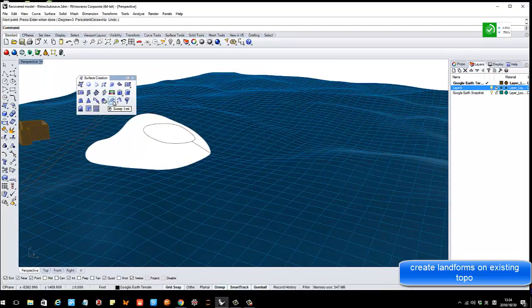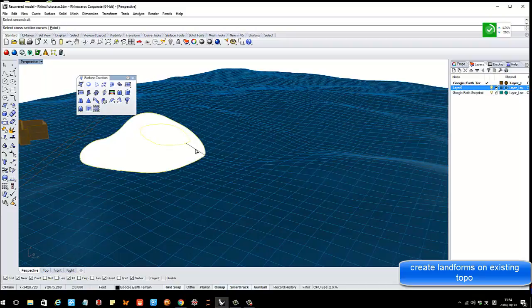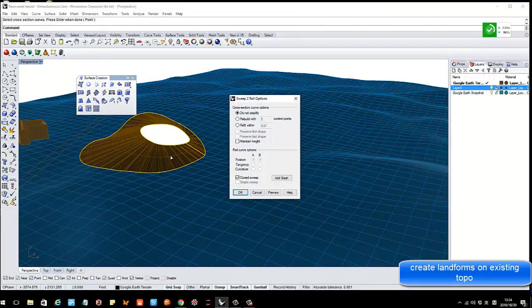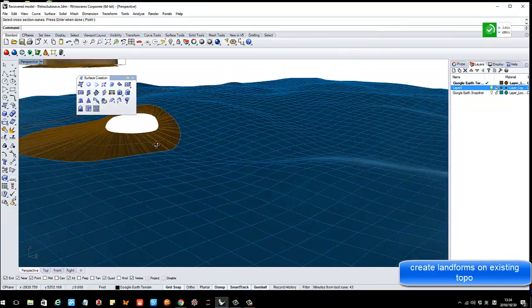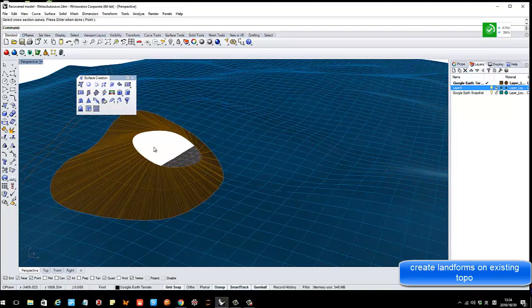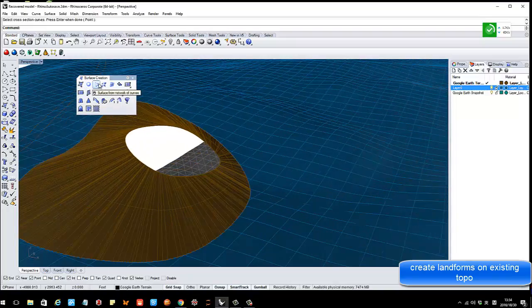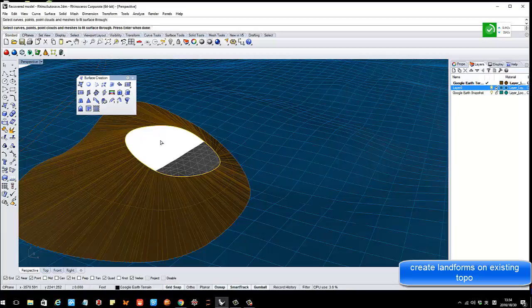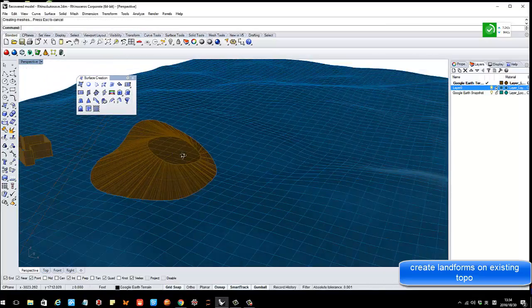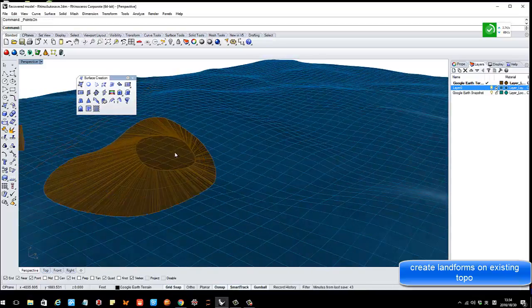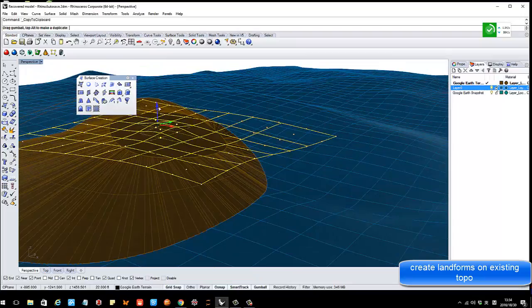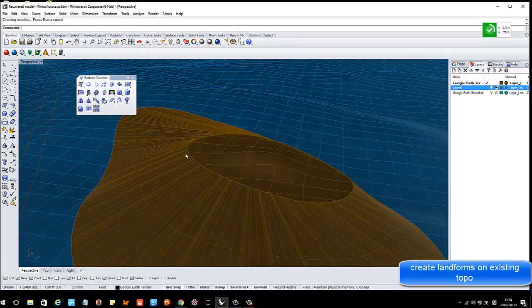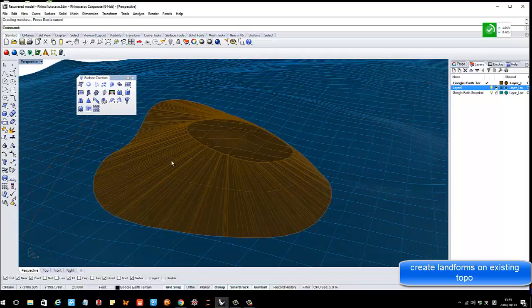And then we just did that before, right? We can do a 2-rail sweep. See here, sweep 2-rail. Select the first one, then you select the second one, and select the cross section, and right click. Then they created some grass lawn area, right, with some slopes you want. And definitely here, this is the top, we just patch that, click OK. Then you create things, right? And here, I can just add the points and select the points and modify, right? It's so easy, you can do whatever you want, okay?